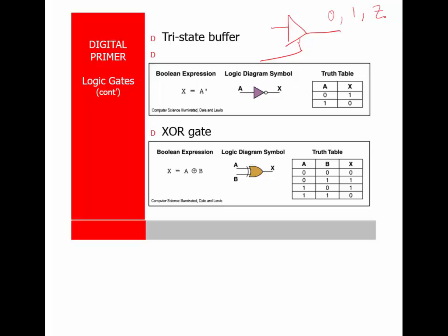But you have, for example, 5 different memory chips. They're all tied to the same memory or data bus. The data bus is the highway, and we'll get to that toward the end of today's class, that contains information that's being passed back and forth. Only one device can put data on that data bus at a time. If 2 devices try to do that, it will usually cause things to malfunction, chips to burn up, bad things happen. So you have to design the system in such a way that only one chip can write to the data bus at a time.